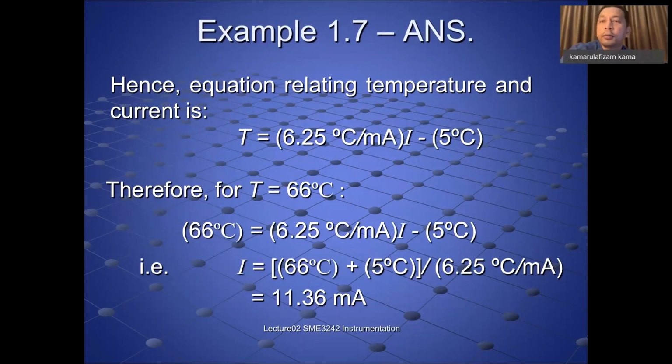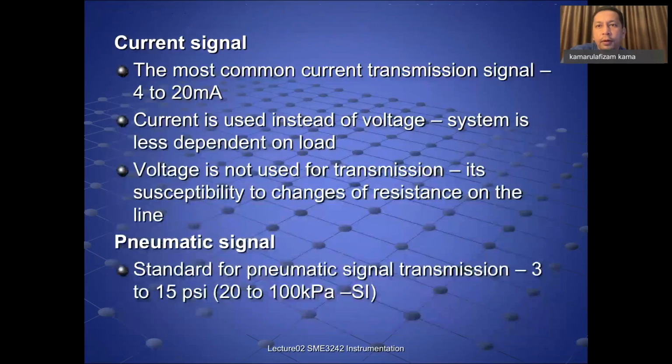But in some other situations, instead of voltage, they can use current. As a standard form, the current only takes 4 to 20 milliamps, and to do this you need a translation circuit to translate this range of current into a range of voltage, because typically the system will read voltage more than current.